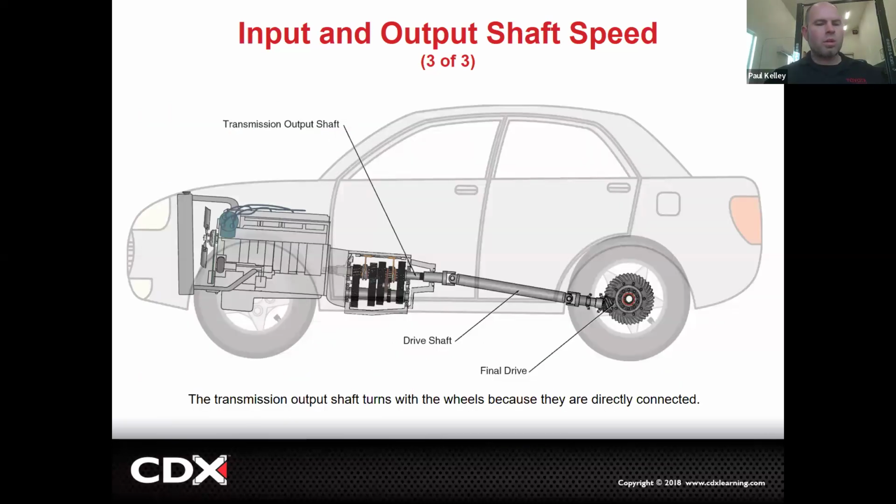That's what this one's showing. Here's the gears in your transmission. If you want to select a different gear, no problem, but you can't do it while torque is coming through the crankshaft. Make sense? I guess technically you could. Has anybody ever tried to shift without lifting? The no lift shift.